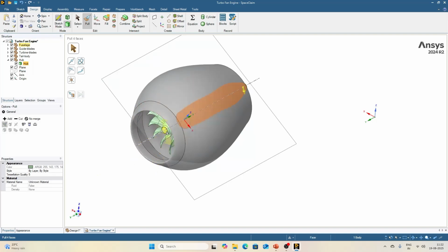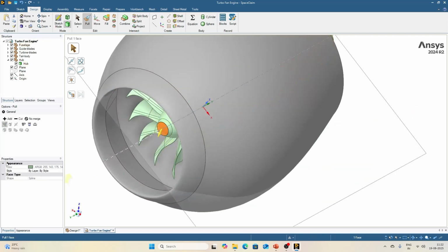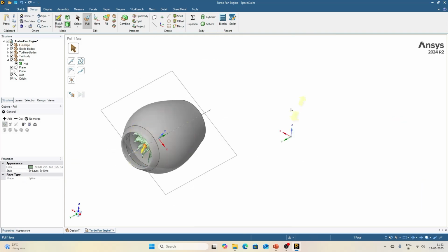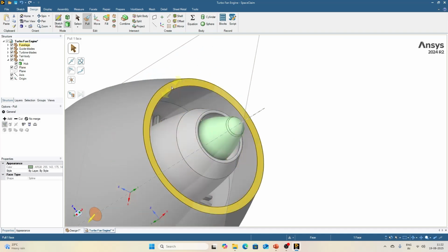If you select any surface, then it will show the surface definition. For example, the surface we selected, this is the geometric definition of the surface. So it is set as spline right now. If it was any flat surface, it will be different, as a plane. So depending on the geometric definition, it will display the information. So depending on whatever we select, it provides the information.